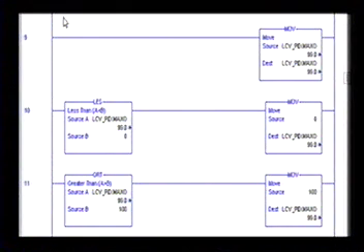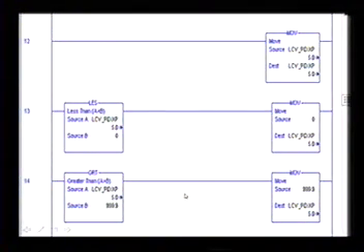Okay. So next we have the level control valve PID max O. We'll move that value into this PID max O, and the reason I did that is just so I could see it, right? A lot of times I'll do that. If PID max O is less than 0, then we move a 0 into it. So we're doing the data validation. And then we say if PID max O is greater than 100, we'll move a 100 into it. So we make sure that it's within 0 to 100%.